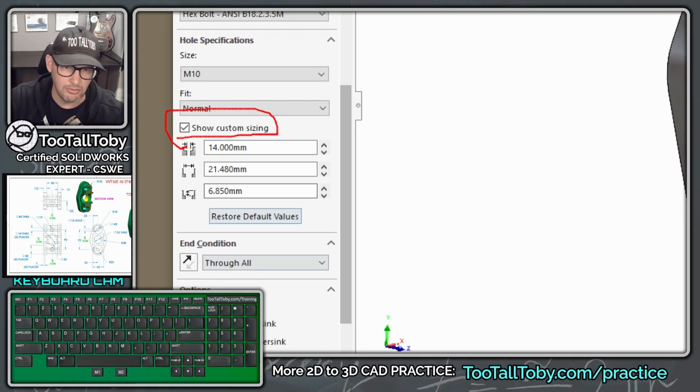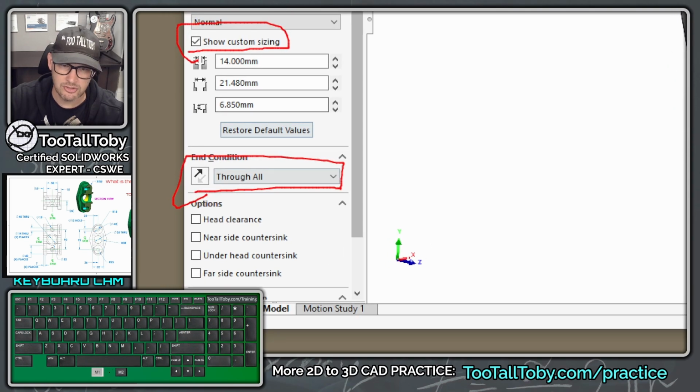Make your end condition through all. Maybe just take a moment, make sure your end condition is through all. Make sure none of these are checked down here. None of these should be checked. That should be through all.